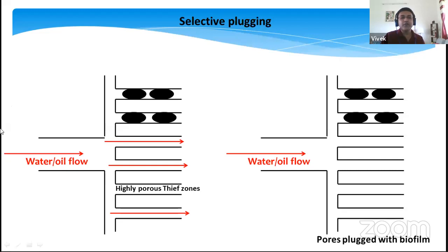While you pump in liquid through the secondary reservoirs to push the oil, you will also find some places which are oil free. Naturally, the water you are pumping will go through these highly porous zones. That means your pumping won't be efficient, as the fluid takes the channels where there is no oil. So this becomes a futile process.